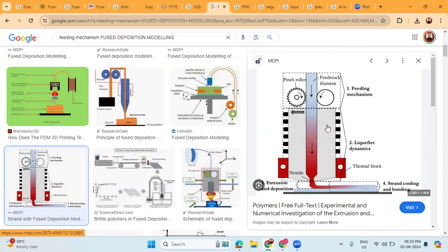omega r is equal to 8 kf into Vt into Wt divided by pi into dr df square, where W and T, we are assuming the shape of the layer is a rectangle, so the area, that means the width into thickness, is W into T. And Vt is the transverse velocity, dr is the diameter of the pinch roller, and df is the diameter of the filament. And kf is called a friction factor.